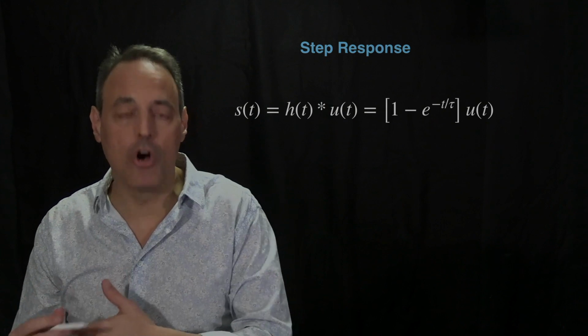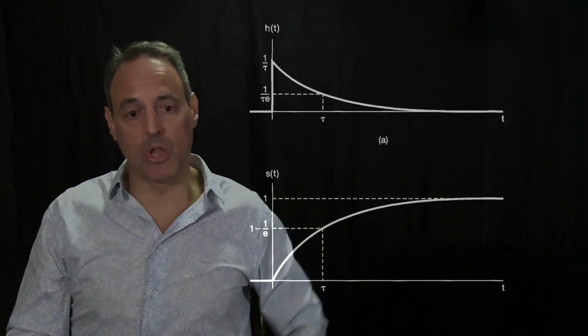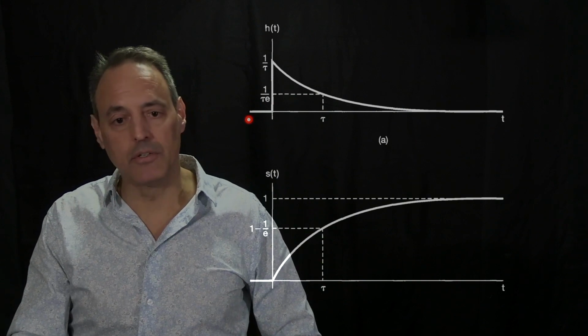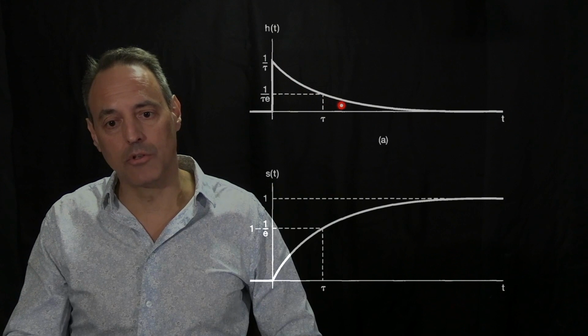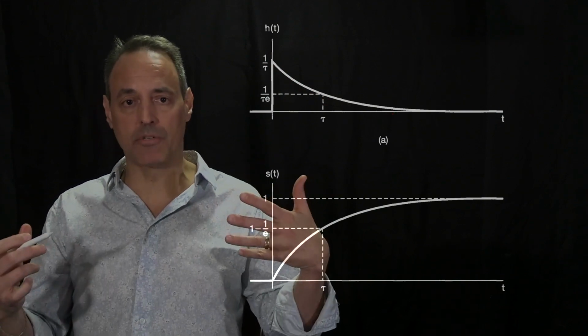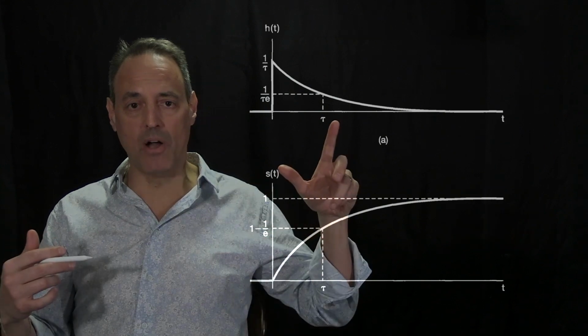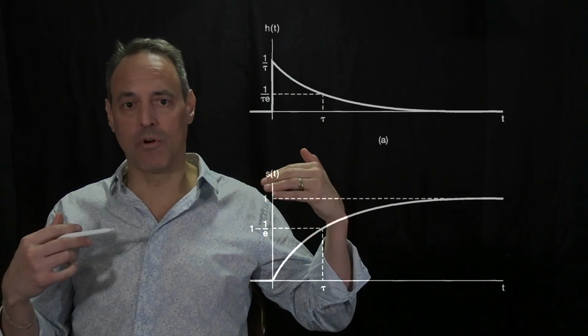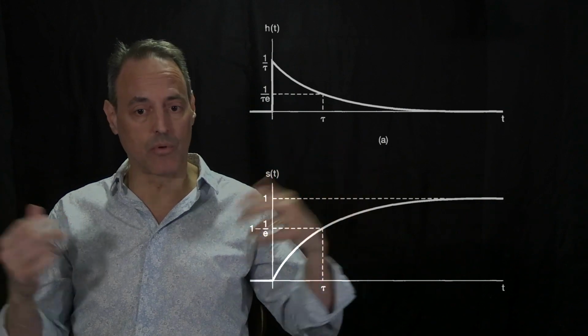So we now know the time response of this. And so here it is in plot. So what you have here, the signal comes, this is what h of t is. It's 0, comes on, goes back down. So that's the fundamental response due to a delta function kick. And we discovered this response by taking the Fourier transform of the actual input-output relationships, which were differential equations.